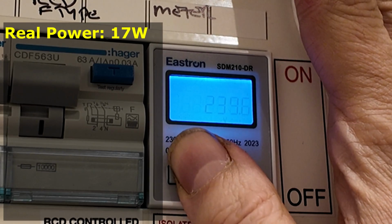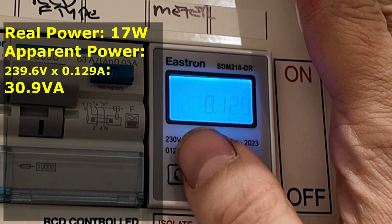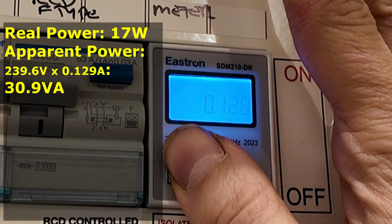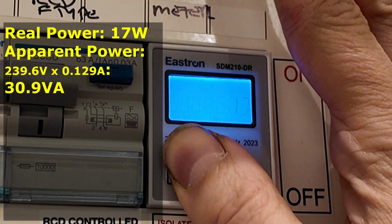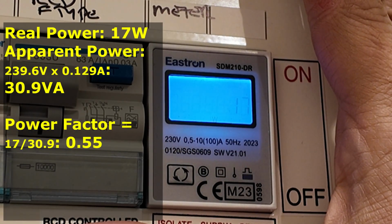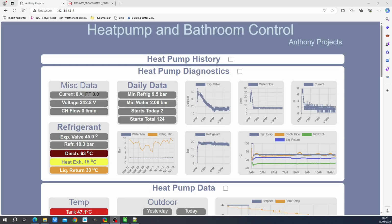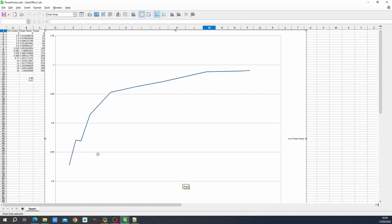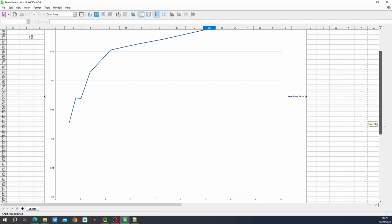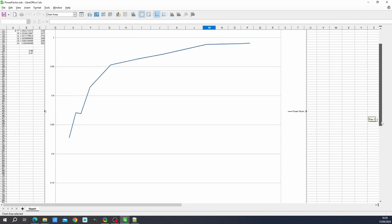Now, if you record the voltage, 239 volts, multiply that by the current, you get what's known as apparent power. So then what you need to do is divide the real power by the apparent power, and you then get power factor. So the result is that you can plot power factor as a function of current, and this is what I have produced. I've charted power factor versus current.